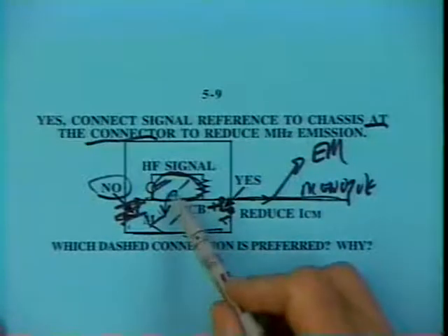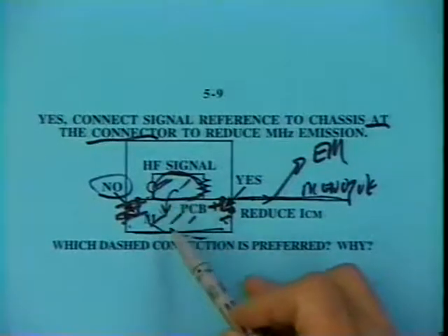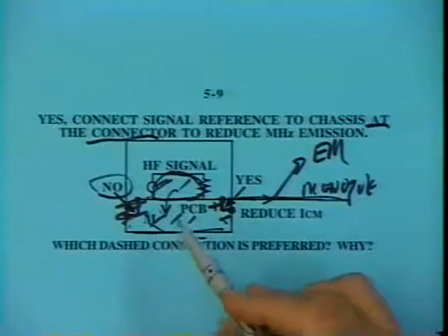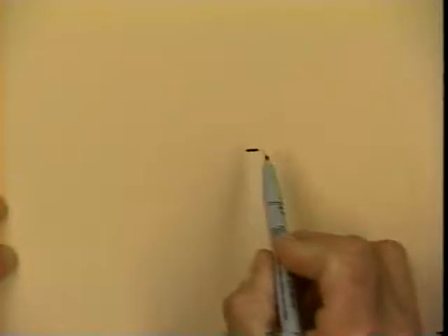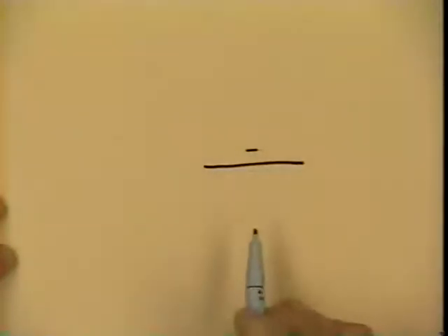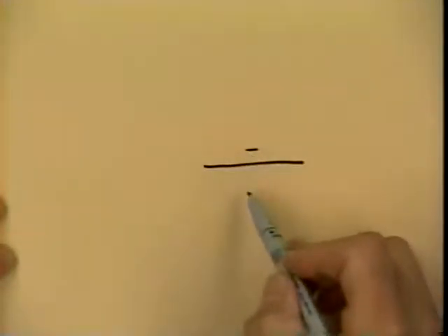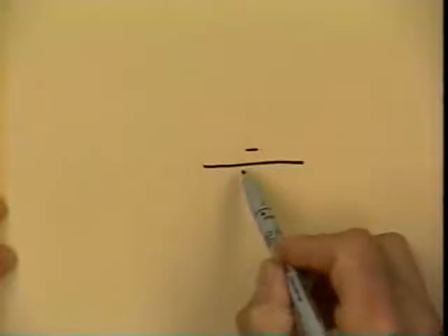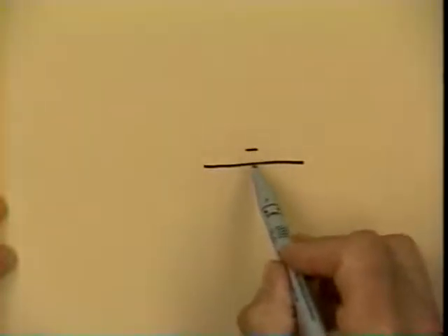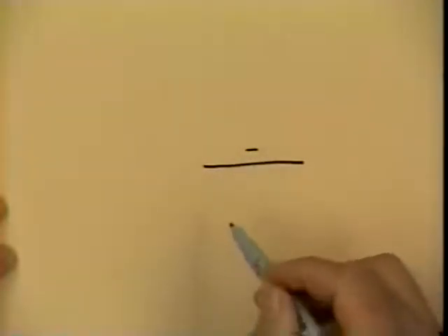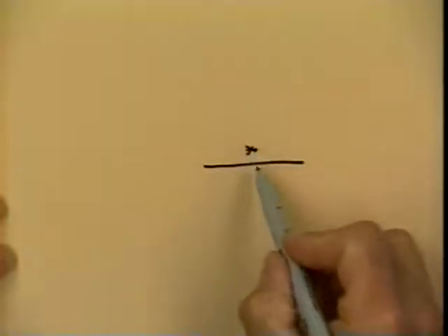Now let me discuss a little bit more about how this magnetic field problem occurs, because this ties in with our first session where we were talking a lot about inductance, self and mutual inductance, and stray magnetic fields and so on. Let's say we have a trace above a plane. And this is our high-speed digital trace, and we're looking at it in cross-section. The current flows into and out of the screen. Okay, so we've got current going in and current coming back out in the metal plate.